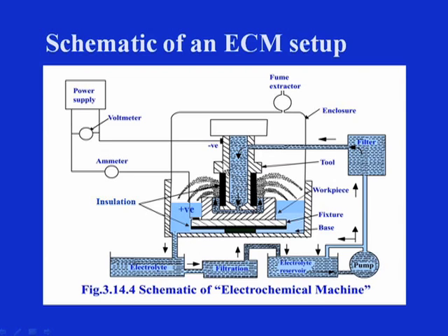Similarly, the tool is also insulated. You can clearly see on the screen, this is well insulated, and the tool as well as the workpiece is connected to the power supply with appropriate polarities. Then the electrolyte will be continuously kept flowing with this electrolyte pumping system, which is in fact a complex